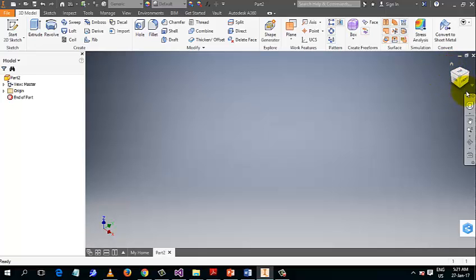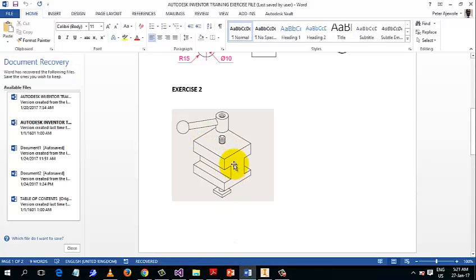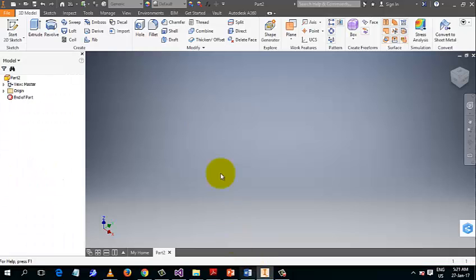Okay, now let's go back to the sketch. So this is our front that we want to draw. So I'm going to create a plane facing that side by coming to origin on the model browser. Come to the origin folder, expand origin folder, and select a plane facing that side exactly. You can see that this YZ plane is facing my front view side. If you click XZ, it's facing the left side, and XY is the top view, aligning with the top view. So I'm going to draw on the YZ plane.